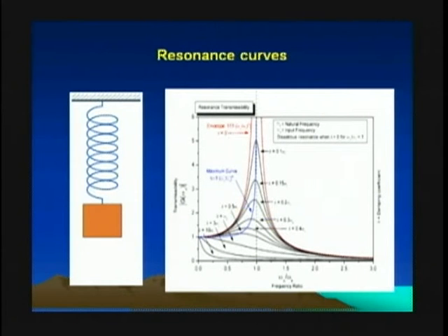So two forces are absolutely crucial to understand what happens. It's the inertia forces, therefore we have a mass here, and the restoring force, therefore we have a spring here. We don't have an excitation force here, we don't have a dissipation force here. So this model is still meaningful, and this is fundamental for understanding the physics of linear vibrations.